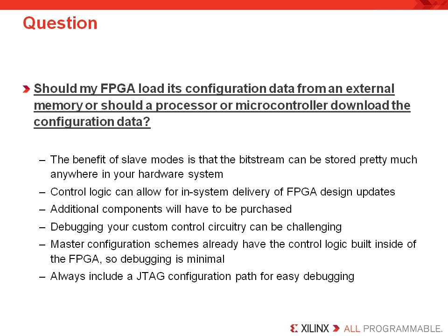Master systems have the added benefit of having the control logic already built inside of the FPGA, so debugging becomes minimal. But regardless of how you choose to load your configuration data, make sure that you consider also supporting JTAG for configuration. This will give a guaranteed way to program the FPGA in case you need to debug your configuration scheme.